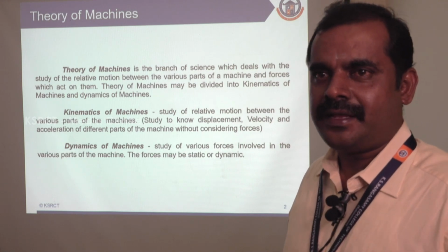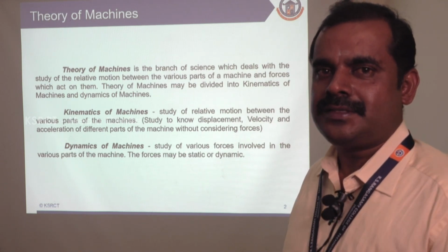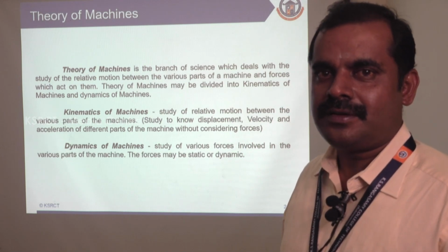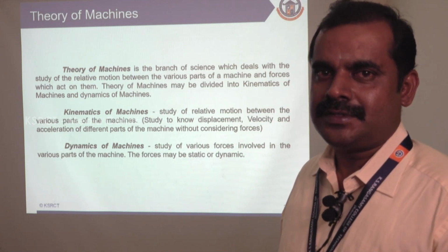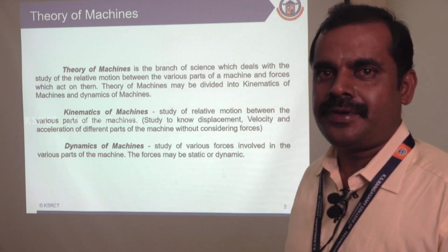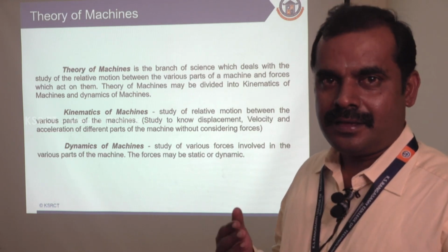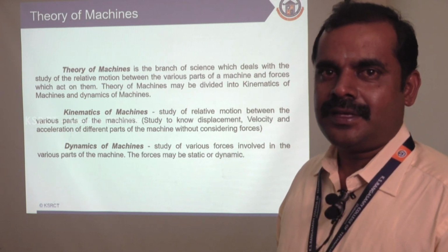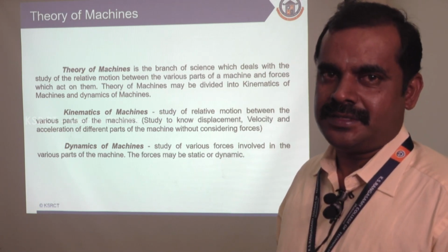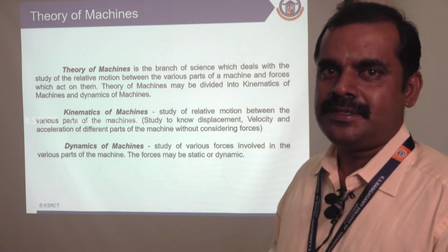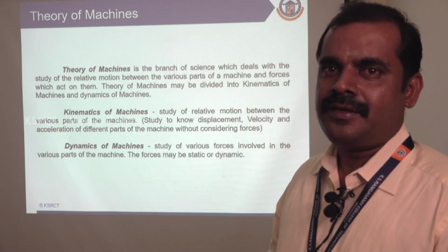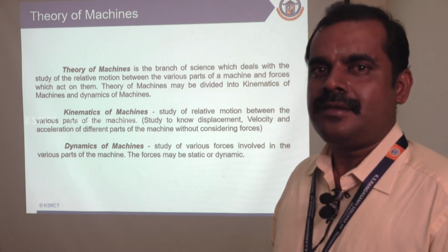Right? The static force analysis means we are not going to consider the inertia forces. Dynamic force analysis means we are going to consider the inertia forces. In kinematics of machinery, we are going to deal with the determination of displacement, velocity, acceleration of the given mechanism or a machine. In dynamics of machinery, we are going to consider the force which actuates the different parts of a mechanism or a machine.